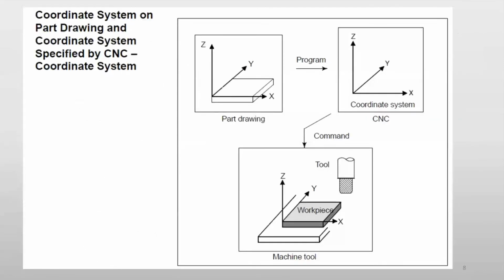When I write the G code, one of the earliest stages of writing the G code, I have to make the machine zero. This is what we call zeroing the machine. Basically, the workpiece that you design as a designer has its own coordinate system, which is the workpiece coordinate system. My machine has its own coordinate system, which is the machine coordinate system, and they don't match. So what I need to do is bring the machine to the coordinates of my workpiece, or technically make it zero. This is something you've done with the machine coordinate system in the software. Do you remember that? The same sort of thing you're doing here.